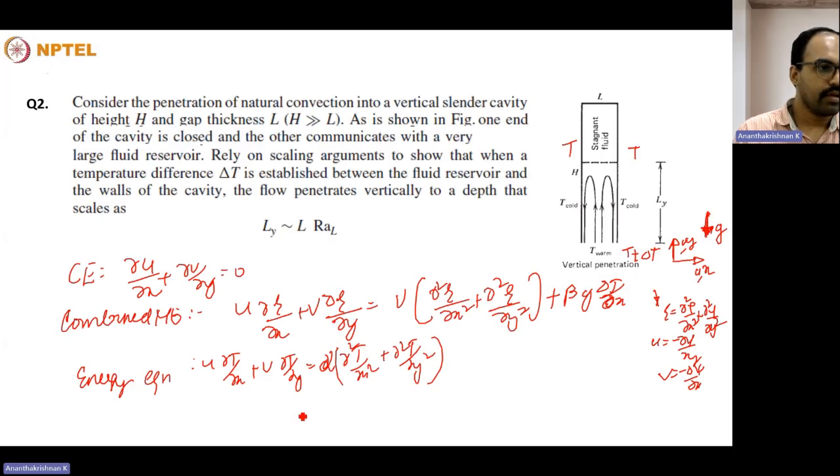What we do is that we use the momentum equation and perform scaling analysis. And just like the previous case, we will get a final equation when we equate. Just similar to the previous case, the left-hand side inertia term will be very much less compared to that of the friction and the buoyancy term. So it will basically be an equivalence between friction and the buoyancy term, and we have to see which out of this x or y is larger.